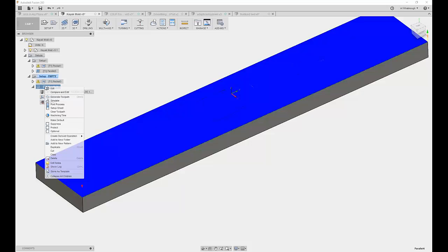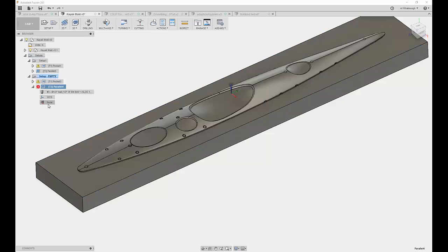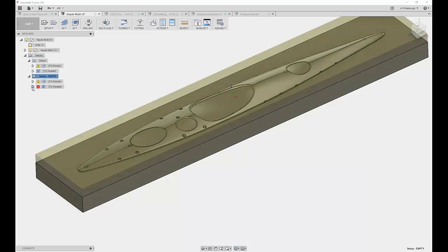There is an ability where we can right-click and clear the toolpath. So see this option, clear toolpath. That emptied the toolpath out, took that 11, 12 megabytes off of the Fusion file, off your SOLIDWORKS file, Inventor file, but everything about this toolpath and how we defined it is still there. So all that has to happen on the other end is a regenerate. So that's a way that you can reduce the file size if need be. Kind of an obscure little trick, but nonetheless, I thought one of those things that doesn't often get mentioned.